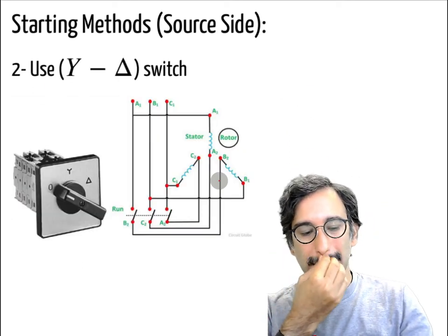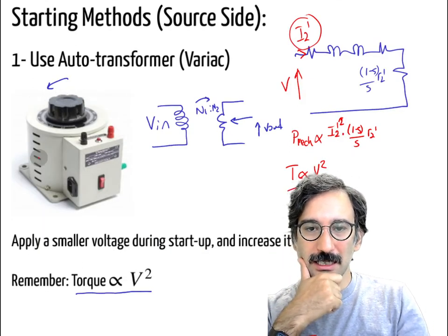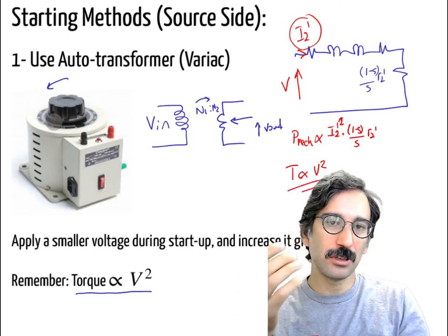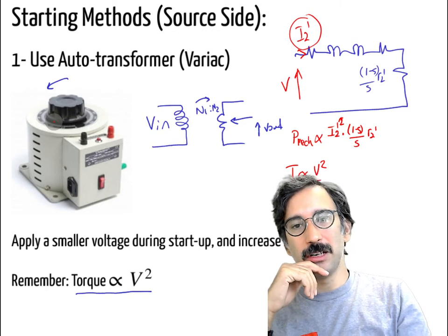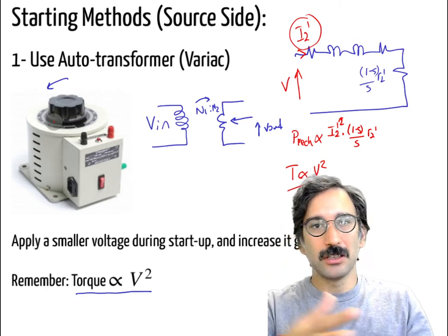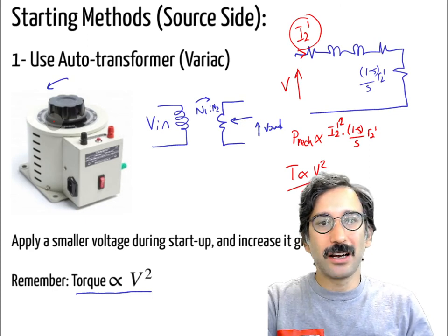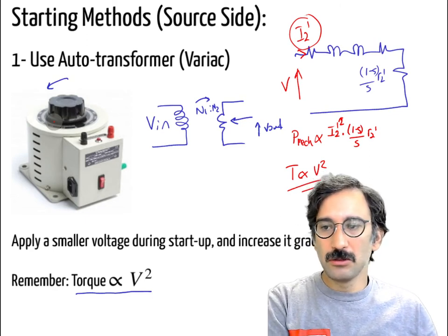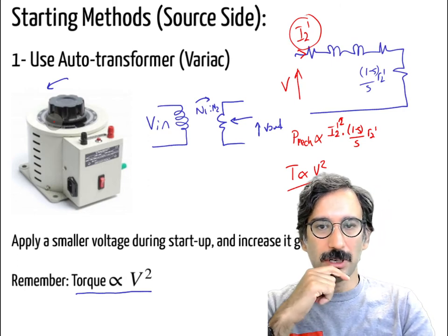Another thing is that this requires external equipment. Again, it's okay for some smaller applications, but for large applications it's not really practical, because you would need a variac as big as, and as expensive as, the motor itself. So that is not really practical.